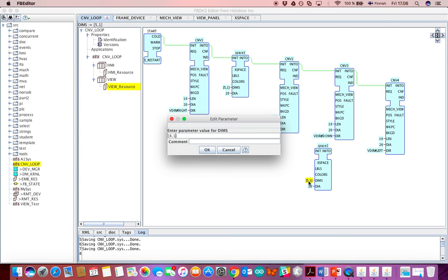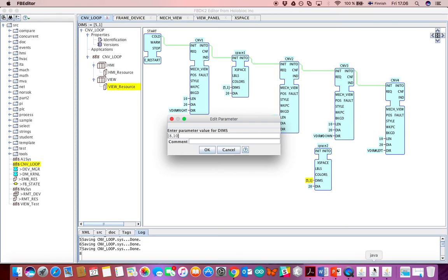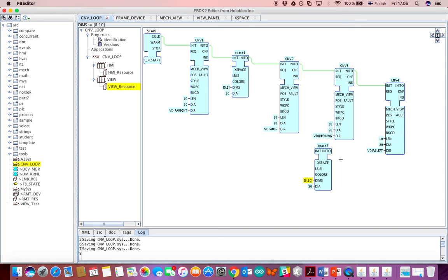And what is the height? Actually, we can calculate, because we fit whole conveyor, we can say it's 10. But 1 would be also enough, because it's row by row filling. And we have already this vertical conveyor 2 and conveyor 3. We do not need to put here, well, exact number. 1 would be enough, but in principle it is 10, which is taking the whole length of those conveyors, conveyor 2 and conveyor 3. Okay. So let me put just explicitly 10, although again it can be just 1.